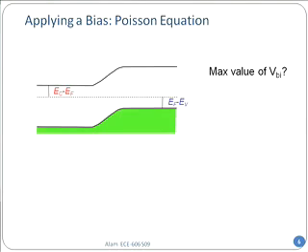By the way, before I go in and solve that problem, let me first ask you this question. What is the maximum value of qV_bi approximately that one can have? We calculated qV_bi, right? With the electron going up all the way to the vacuum level from one side and the electron going up all the way to the vacuum level on the other side. We did the math. But physically, what is the maximum value you can have?